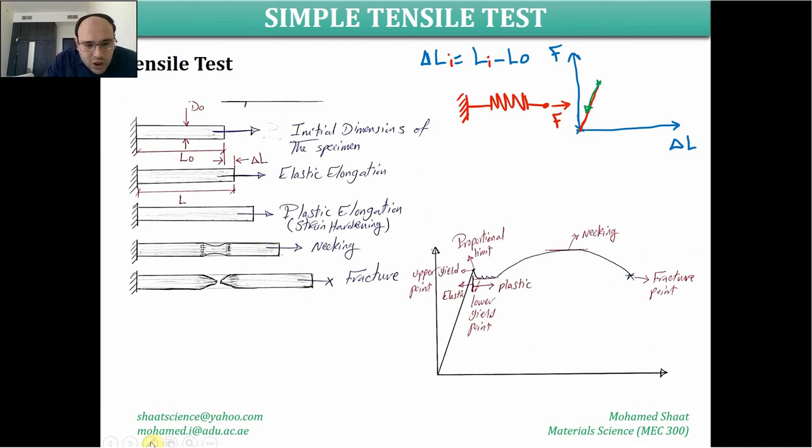But if we keep on increasing the force beyond a certain limit value, the material will move to the yield region or the yield point of the material. Some materials, as already shown in the video, like the first material sample, which was steel, show an abrupt change or a sudden drop in the force within a region. Then the force is almost constant, then it moves to another curve. So this region is known as the yield region or the yield point of the material. This is the transition point between the elastic behavior and the plastic behavior of the material.